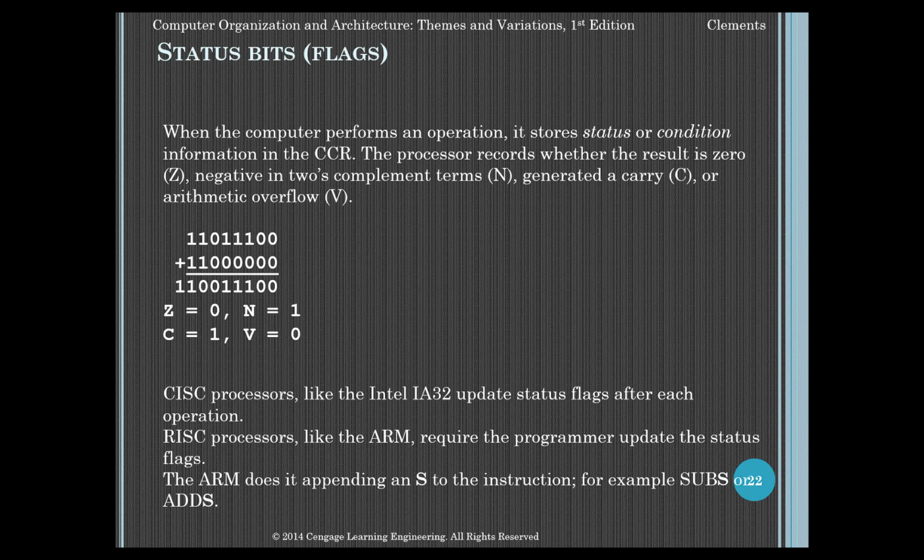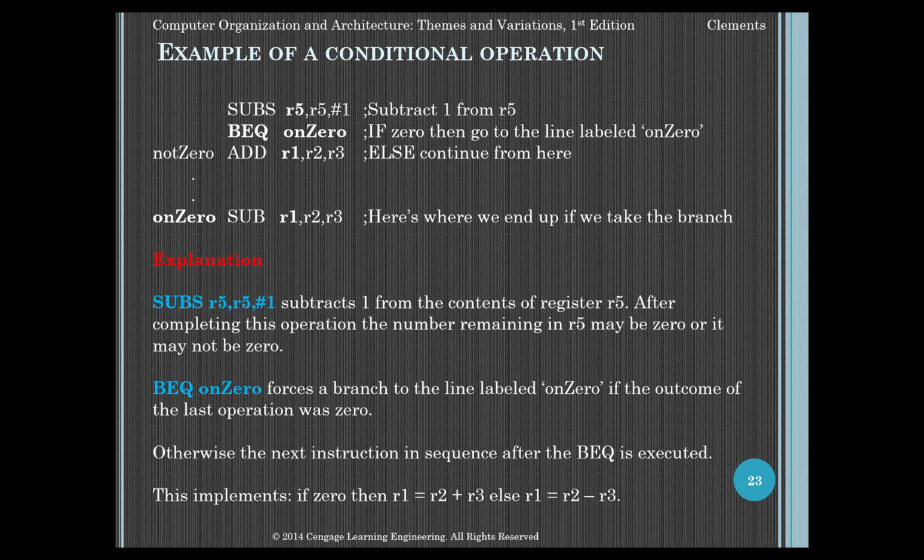First, recall that the opcode field of the BEQ instruction in the IR selects a bit in the CCR to be tested. So the Z or the N or the C. If the tested bit is 1, then the PC is loaded with a new value, such as the branch target address. Otherwise, the PC is not modified.